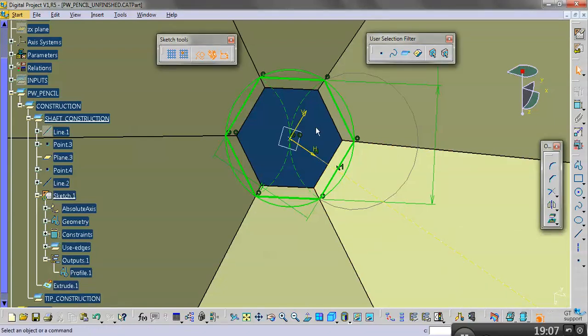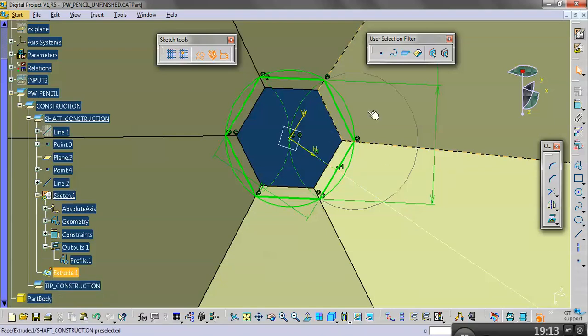So like, will a finished line always look green? In a sketch, yes. In a sketch, it's not finished. A fully constrained line is always going to be green. A normal line is just going to be white. And an over-constrained line is going to be purple or red. Okay. Orange in a sketch means it's construction, orange or dashed.